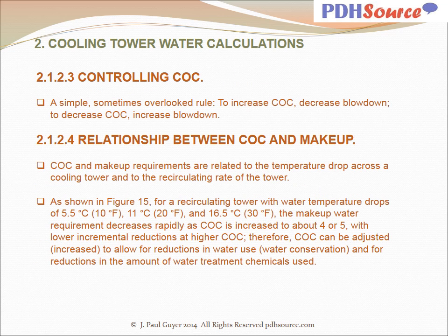Controlling the cycles of concentration, a simple, sometimes overlooked rule. To increase COC, decrease blowdown. To decrease COC, increase blowdown.